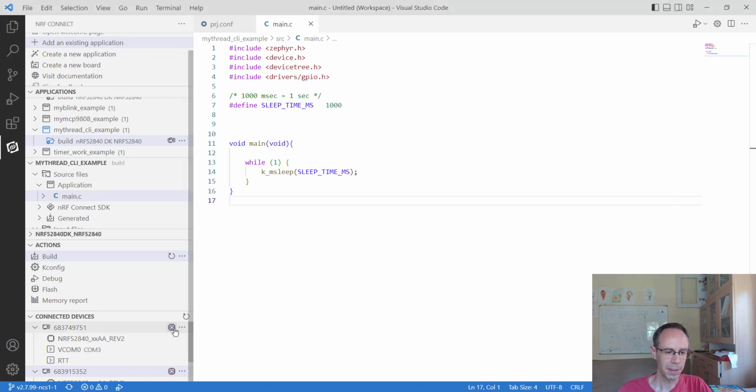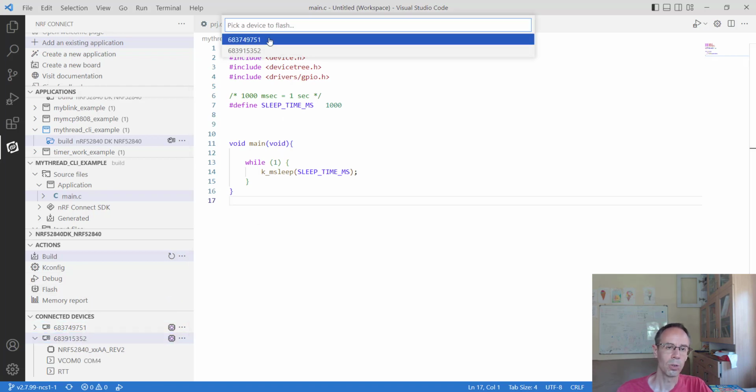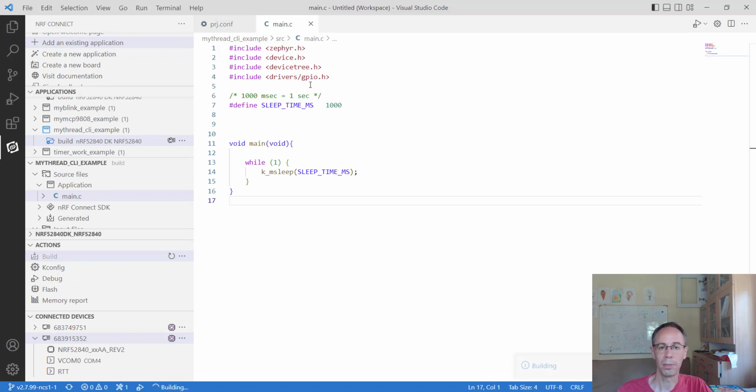And first we transfer the firmware now to the boards. We're going here on flash, but be careful, especially the first time you flash something, set your reset before. So don't go here on flash, go on erase and flash, so that the parameters from the thread stack or anything from before are deleted.